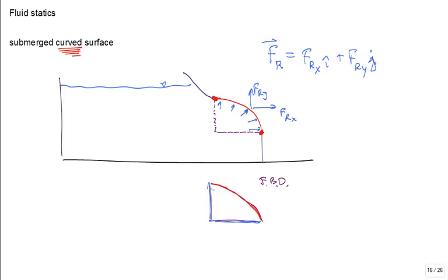So this surface right here has a trapezoidal pressure distribution acting on that face. And because I cut it along the y-axis, it's just pushing in the x direction. True? And because I cut the bottom one horizontal, the force due to the pressure of the water below is acting upward, and it's pushing with a uniform distribution.